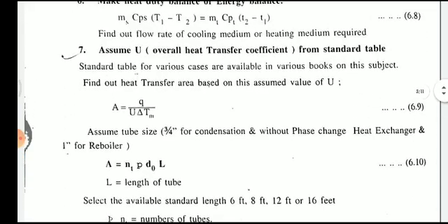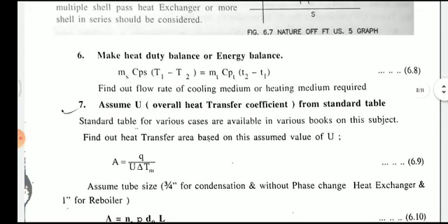Now, heat duty balance or energy balance. The heat duty can be calculated by m Cp delta T, that is for shell side and tube side, the flow rate of cooling medium and heating medium.